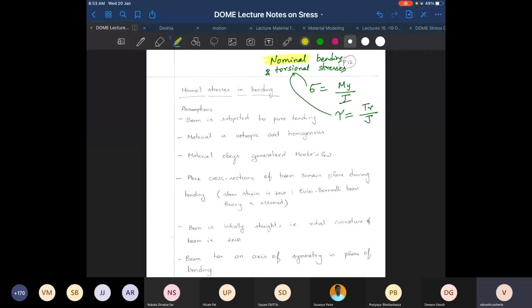This is the minimum stress that is going to get generated. Later on in the class, I'll be teaching you about different features which result in increased values of stress. These features are called stress concentrators, so you will get introduced to the concept of stress concentration. You need to know the nominal stress and the stress concentration factor in order to find the maximum stress acting at a particular point.